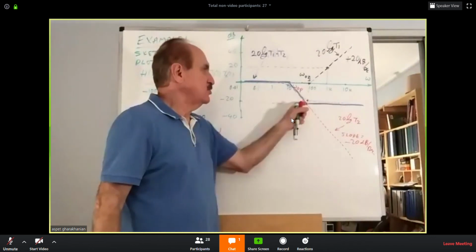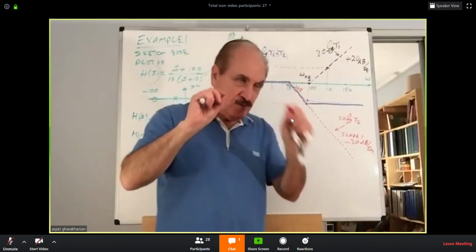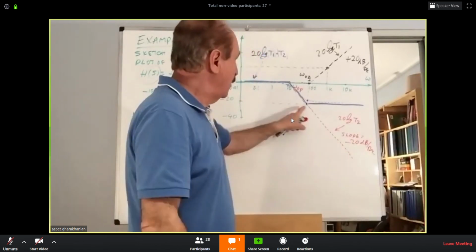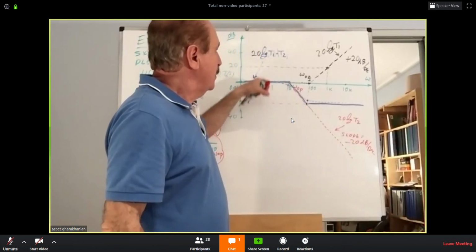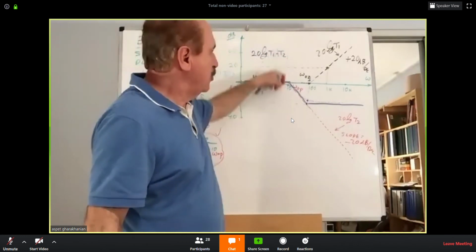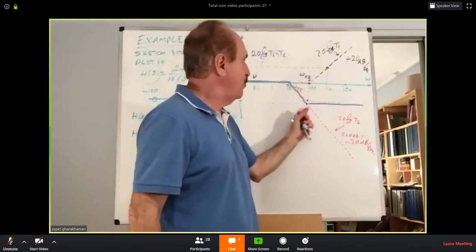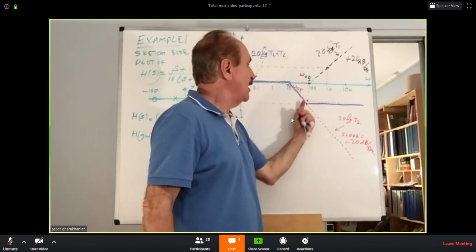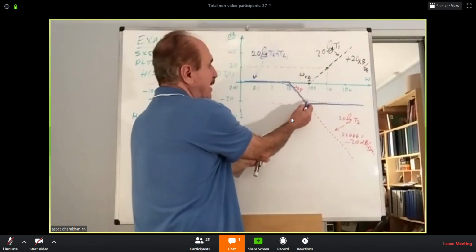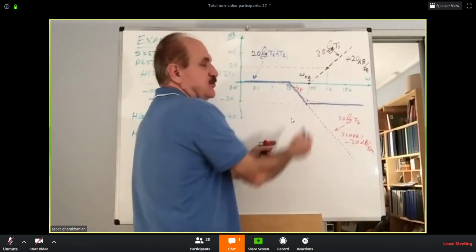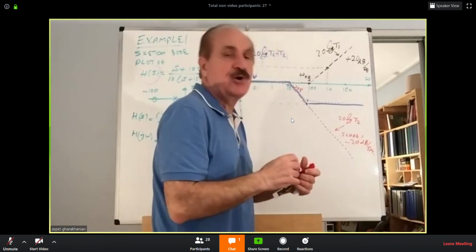If you need to shape them or smooth them out, that's the way to do it. But always be aware of the corners. If it is looking down, it's from a pole, so it has to go 3 dB down. If it is looking up, it must be from a 0, so it has to go 3 dB higher. So that point should be actually -17, which is 3 dB above the -20. So that is called the correction.